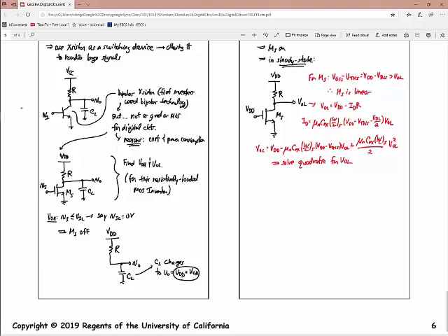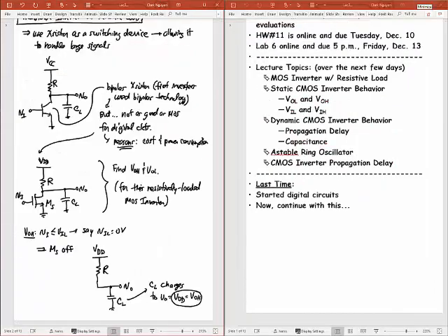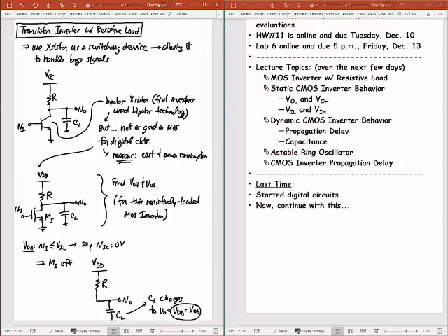Okay, so there's this transistor M sub S here, and I guess I have this in the actual lecture material too, so let's just go to this here. So we were looking at this transistor inverter with a resistive load. You can make it either with a bipolar transistor, but we criticize that, saying that it costs more because bipolar transistors are larger. Plus, there's power consumption that we don't want that is going on while we do this. So we don't do this necessarily.